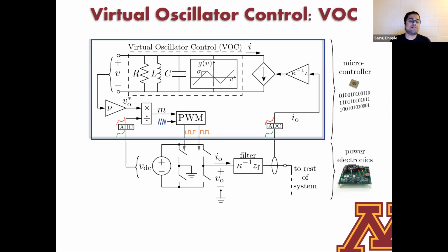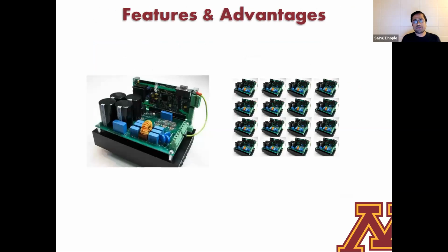The one thing that I want to draw your attention to before we go ahead is that this is entirely implemented in real time, right? So there's no notion here of frequency. There's no notion of average power, reactive power, no additional computations that I'm hiding from you beyond what you see, which are the physical dynamics of this oscillator circuit all by itself. So that real-time aspect of this, we'll see, is going to give us tremendous opportunities for improving performance, especially over phasor domain-based methods.